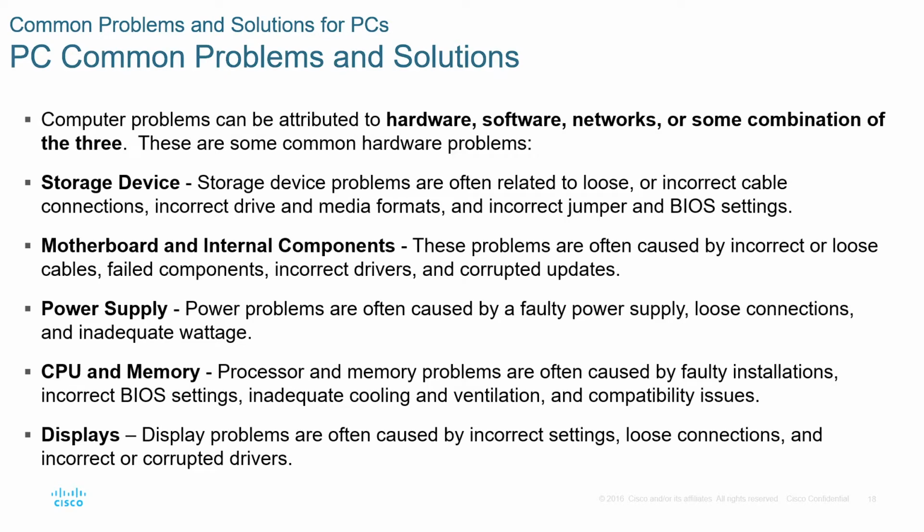manufacturer's recommended temperature. We may also have display issues, and those display issues may be caused by incorrect settings, they may be caused by loose connections, and they may be caused by incorrect or corrupted drivers. Okay? So if you just notice here for a second, one of the most common issues that is related to a lot of the problems that we have just listed is the loose connections.